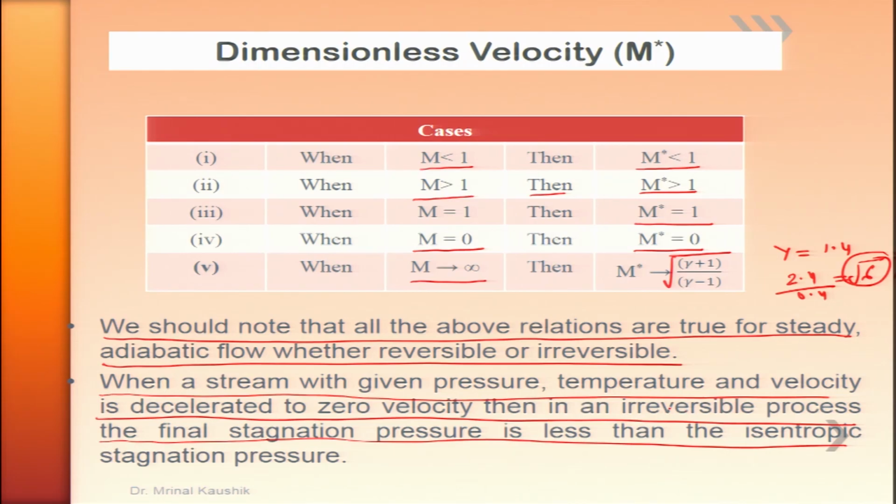Also, at this juncture, I want to clarify that all these analyses, these relationships which we have established, are true for both reversible and irreversible cases, because for every relation we derived, we started with adiabatic, inviscid, non-conducting flows, the application of the energy equation. Therefore, all these relationships are valid for irreversible as well as reversible cases.